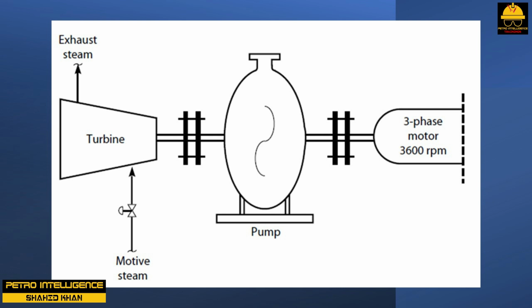If I had not remembered this prior to cooling the hydrocracker feed, the motor would have tripped off. As it was, I had the steam to the turbine increased so as to decrease the motor amps to 60% of maximum before cooling the gas oil. Omission of this detail would have had embarrassing and possibly negative contractual consequences.